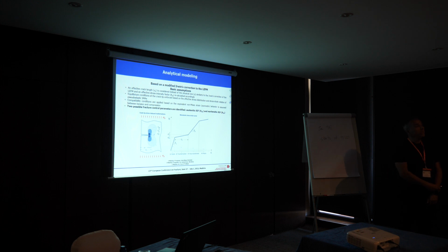Okay, so how do you extend the crack, or is it just a calibration? So you're not modeling explicitly a crack growing and making decisions based on that effective stress intensity factor, is it? So we just consider the crack length, and at a given size of the crack length, we recalculate the stress intensity range. Understood.